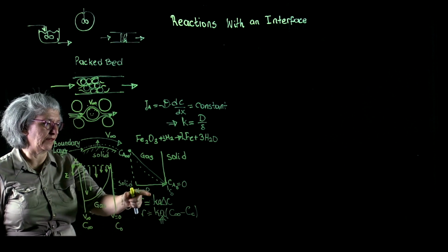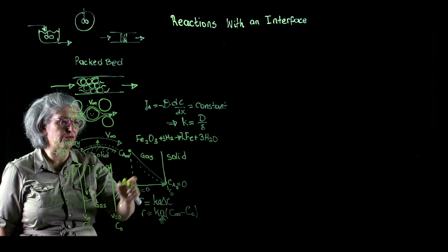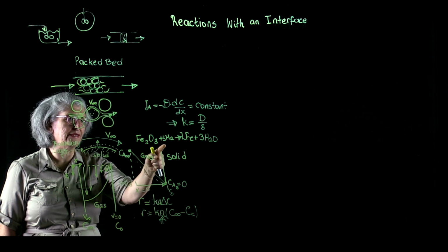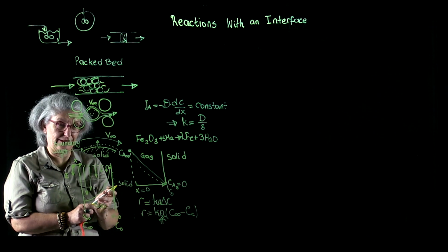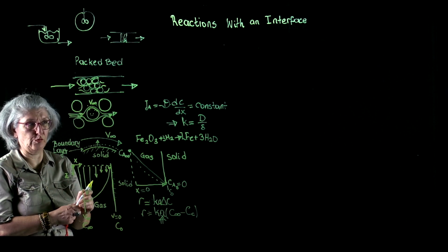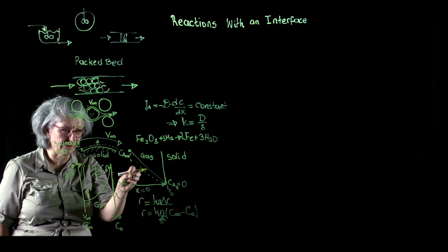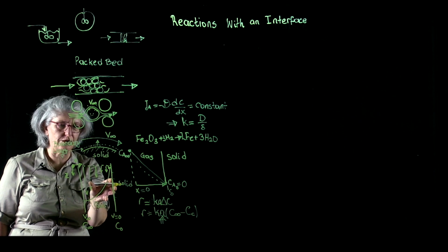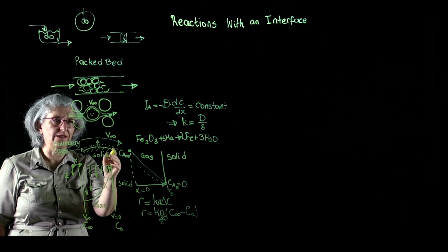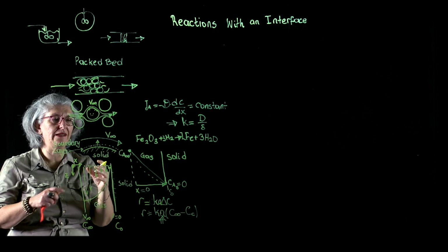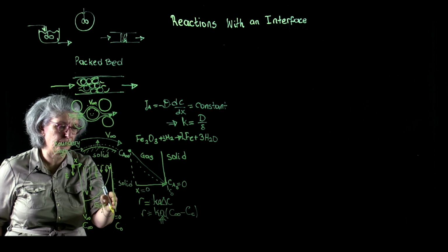We know the gas phase concentration profile. Now the question is how the solid will behave. This time we zoom out and shrink our perspective. Let's look at the solid side. On the solid side, you can imagine that we will have a moving boundary, that the surface of the solid will be reduced.